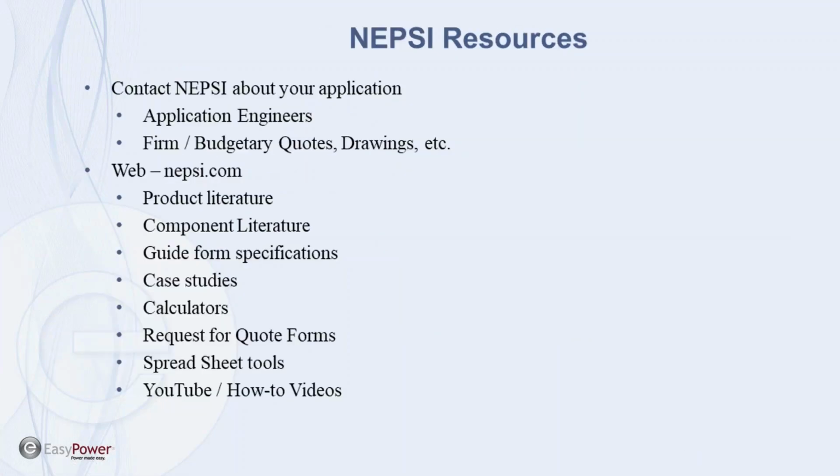So that kind of completes the presentation. I did buzz through this pretty quick because I have a hard stop at 2 o'clock. I do encourage people to check out the spreadsheet tools and also to reach out to me. I stress that having the ability to specify harmonic filters is a plus for your organization. If you're involved with consulting or EPC work, you will save your clients a significant amount of money by taking the filter design responsibility from the possible supplier of the nonlinear load devices.